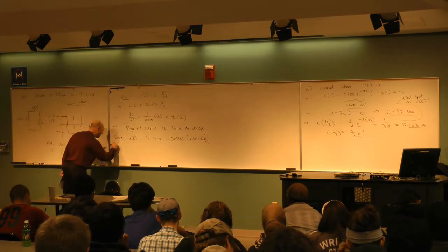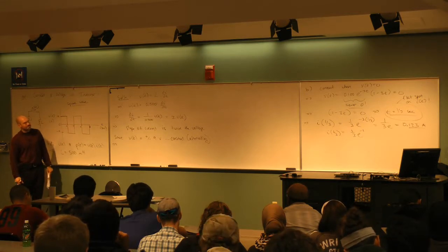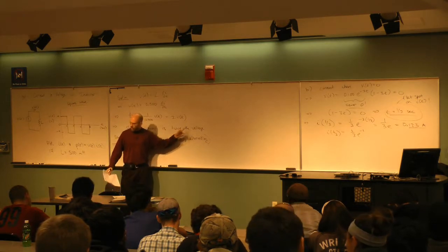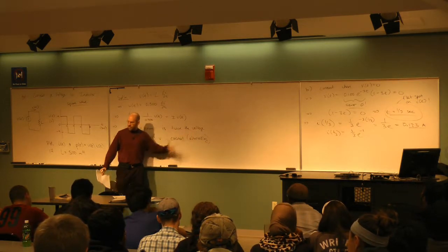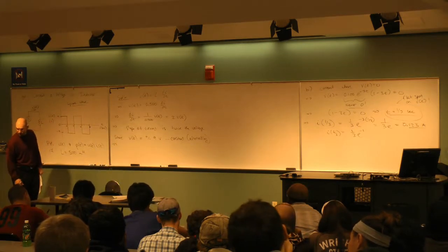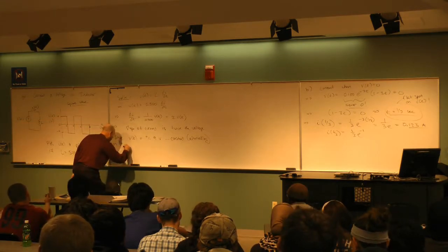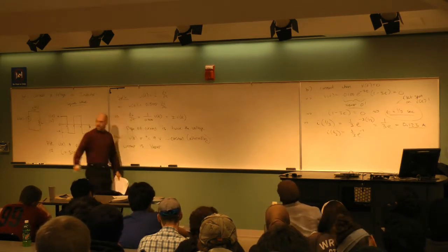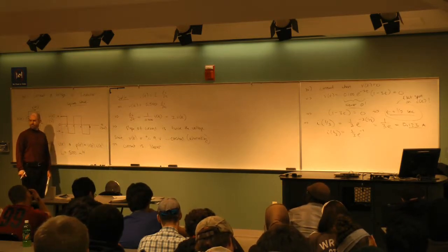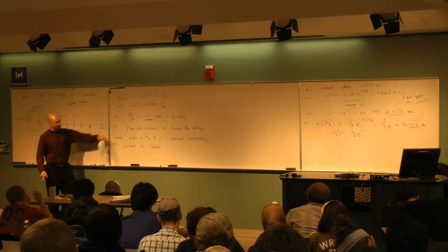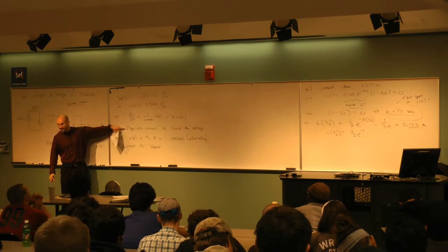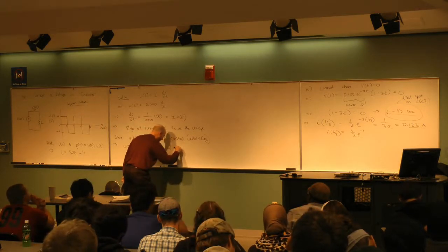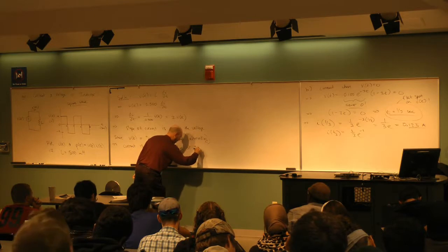And so if that's true, if V of t is constant, and the slope of the current is twice whatever that constant is, then what kind of function is the current? Yeah, the current is linear, right? Do I know what the slope of the line is? So the word says the slope of the line is what? 18. It's twice the voltage. Is linear with a slope of plus or minus 18.